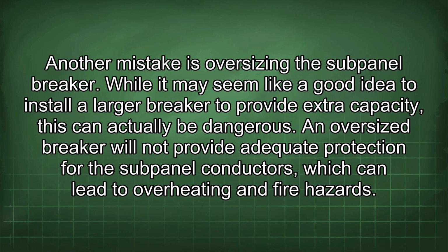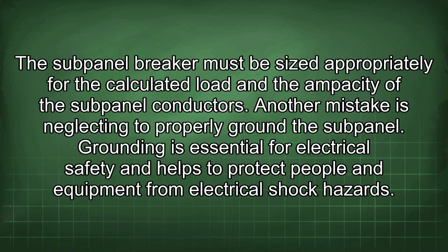While it may seem like a good idea to install a larger breaker to provide extra capacity, this can actually be dangerous. An oversized breaker will not provide adequate protection for the subpanel conductors, which can lead to overheating and fire hazards. The subpanel breaker must be sized appropriately for the calculated load and the ampacity of the subpanel conductors.